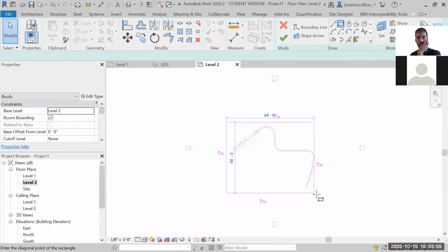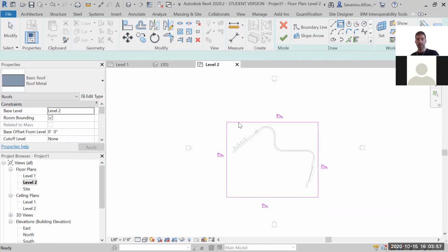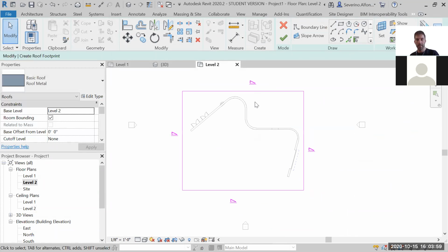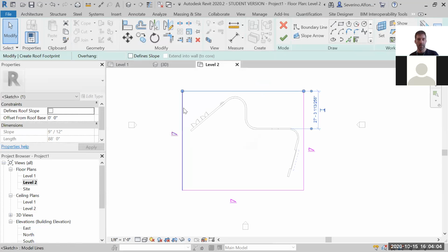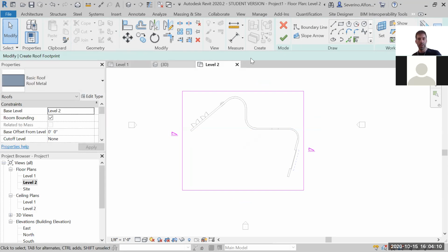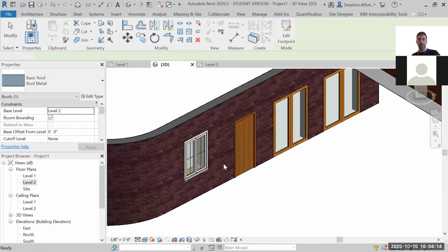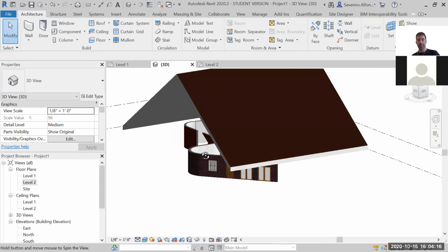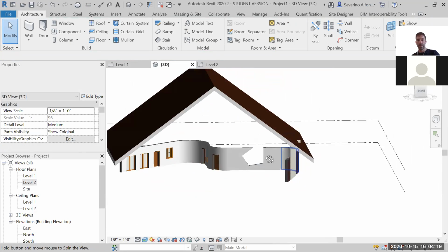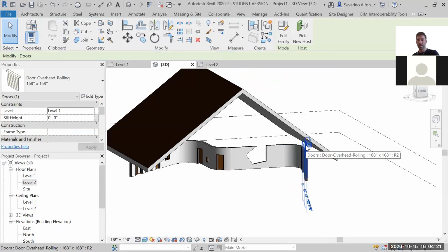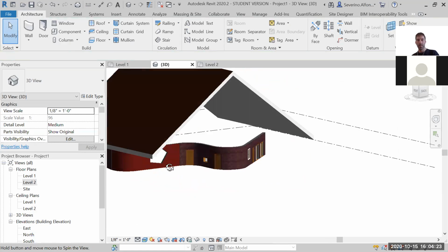You create a roof. Remember, we mentioned this idea of tilted roofs or in an angle. You can select them and uncheck the finish slopes. And you can leave any other line with a slope. If you say okay, that will be sloping in 2 directions, like here, no? Okay.